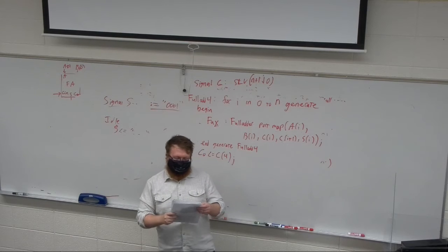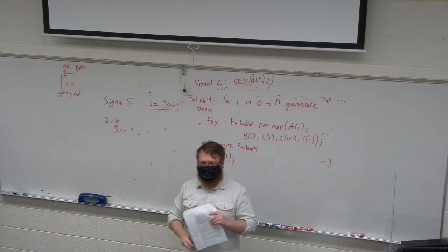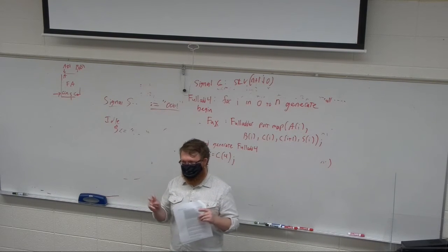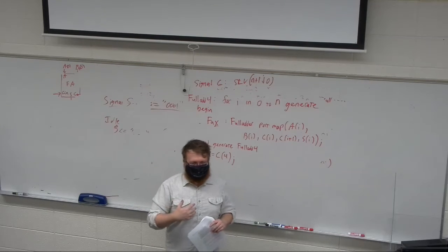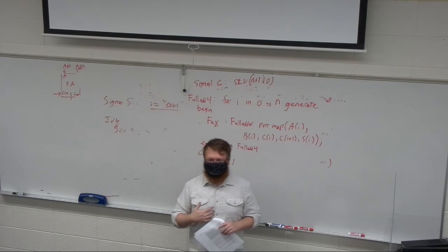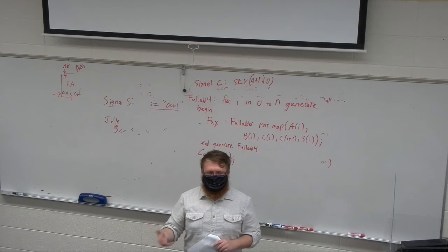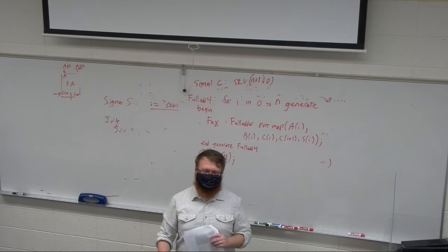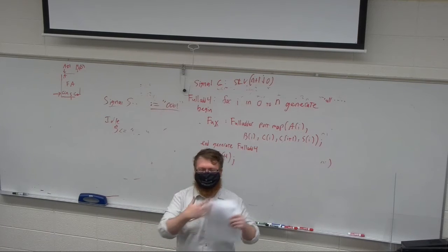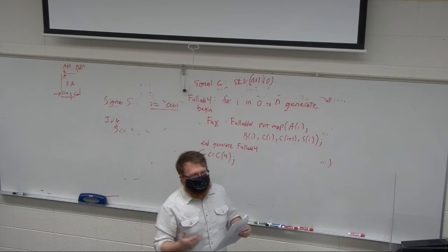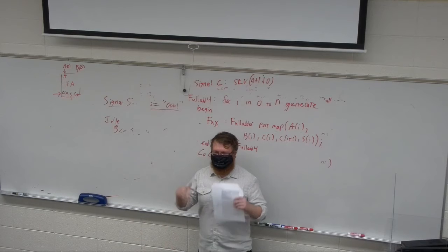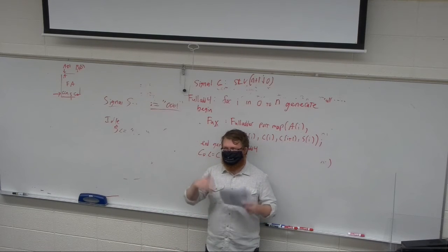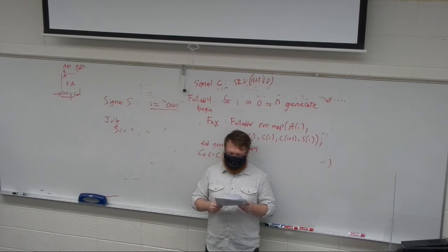It also avoids what they like to call in this book implied operands or side effects. Now, personally I love implied operands when I'm designing FPGA logic. The most prolific example of these is what we call flags. And I've talked about using flags in the I2C to dictate if a condition is true. RISC hates flags. It just wants to use the basic commands because flags can get out of control really quickly if you use them everywhere. I love flags though, so my design philosophy is at odds with RISC.